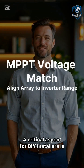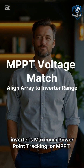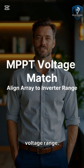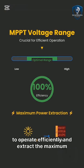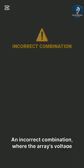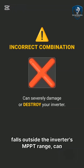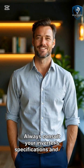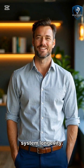A critical aspect for DIY installers is matching your solar array's voltage to your inverter's maximum power point tracking, or MPPT, voltage range. This range is crucial for your inverter to operate efficiently and extract the maximum power from your solar panels. An incorrect combination, where the array's voltage falls outside the inverter's maximum power point tracking range, can severely damage or even destroy your inverter. Always consult your inverter's specifications and plan your wiring carefully to ensure compatibility and system longevity.